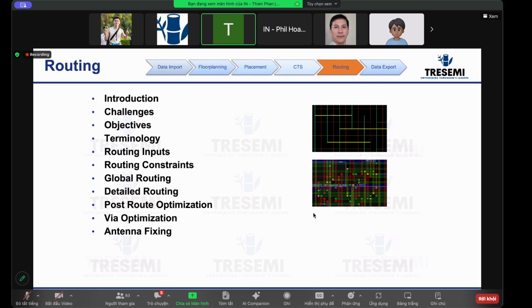And once in a while, that happens to be the key difference between the global route and the detail route, right? Locally, there's some crosstalk. So you have a long wire running in parallel, and then it's just bad. There's no congestion, but the tool didn't look at the crosstalk. So all these long wires are just running along, and if you don't look at the crosstalk, they are perfectly fine. But when you look at the crosstalk, they're problematic.